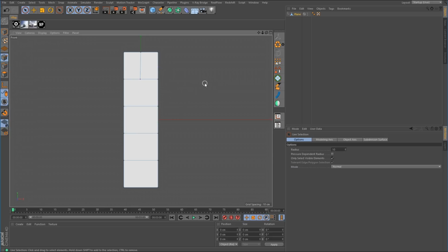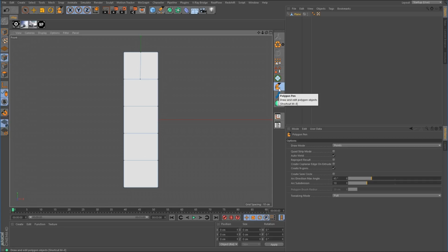In order to solve this, there's a couple of different ways you can do it. The first way is to make a cut across, take this point here and just continue the cut down, and then weld that point down to there. Now we've solved the problem. Now we've got a quad here, and a quad here. So we've gone from 2 to 3 down to 1. So that's one way of solving that one.